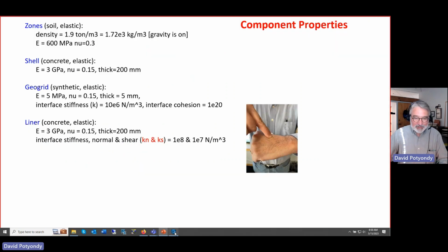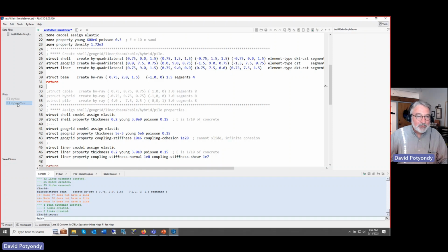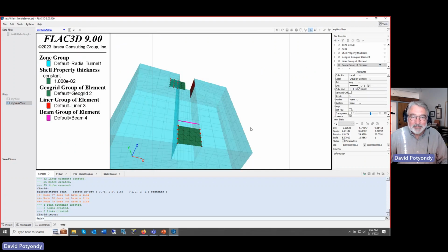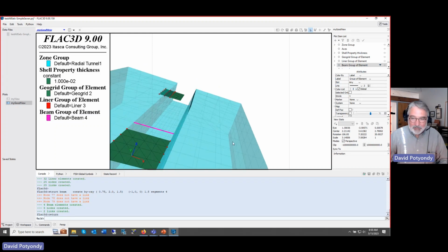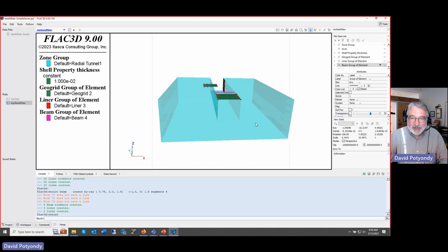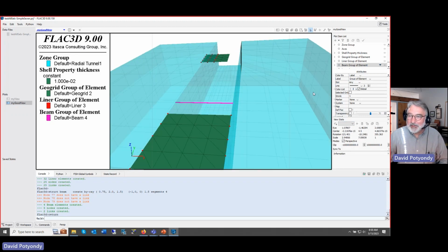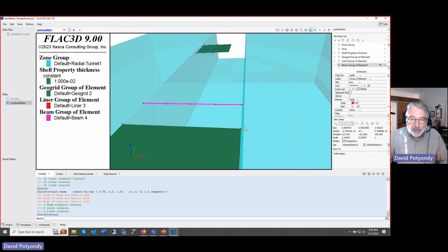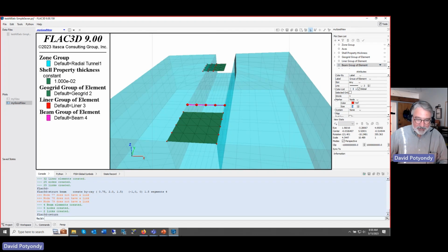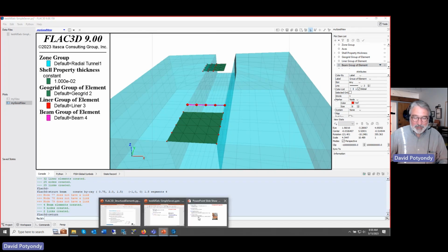Let's just confirm that. We look at the view and you'll get, I bet you know what's coming up here, a beam plot item. And there's my beam. Let's go and reset model view because I've got myself kind of messed up here. Let's zoom in. There we go. Let's look at the nodes on that guy. Marker, node, boom. You can see, I don't know, can you see? There's nodes. 5 nodes, 4 elements. Looks good.